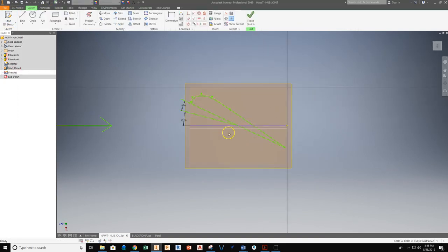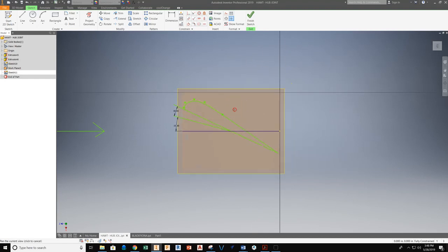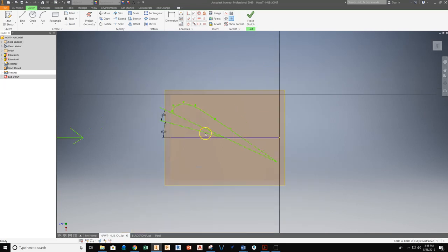They directly overlap each other, which is great because all I really want to set up now is the twist. So we're looking at a twist from root all the way up to the tip of the blade, somewhere in about 10 to 20 degrees. So I'm going to go pretty extreme, where I will need to project the geometry from the first sketch so that my center is the same, and then I can find center.